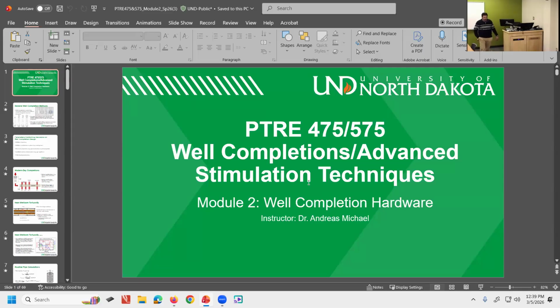I did mention in class at least twice that, with some variation in the context, leak-off testing is not specifically measuring SH mean, it's measuring S3, the least compressive in situ stress.